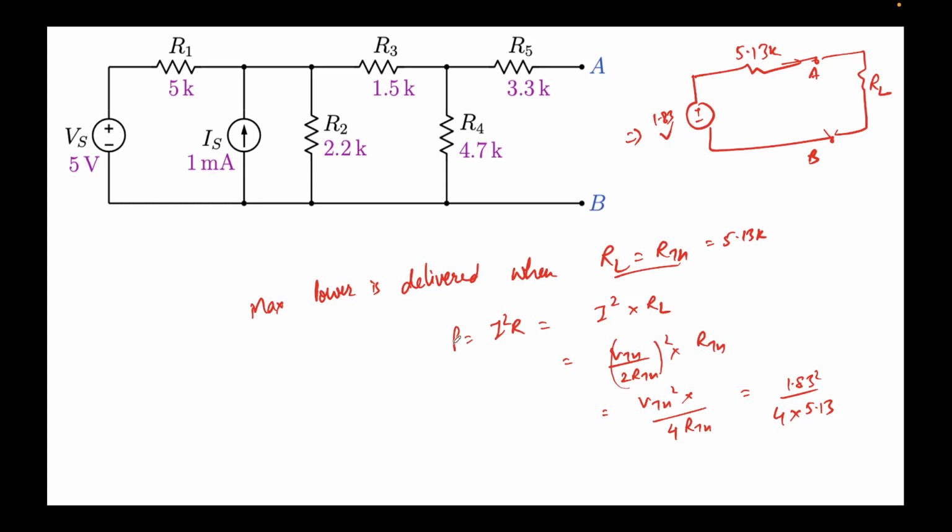This one, the power calculation, sir, I square into RL? Okay, sorry, I made a mistake. I is the current flowing through this circuit. So power delivered to the load will be I square times R. So what is the current? Current will be VTH over RTH plus R.